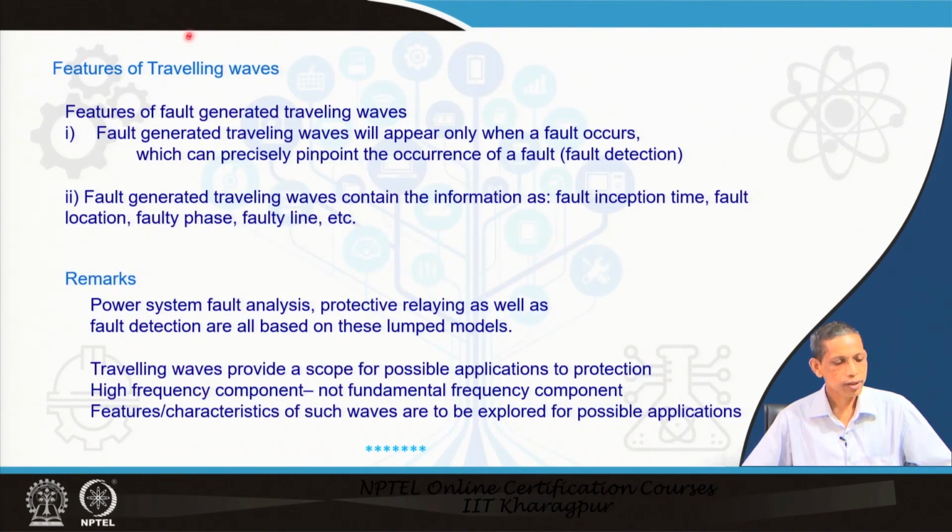Now the features of travelling waves. Fault generated travelling waves will appear only when a fault occurs. We can discriminate between fault and load change, which can precisely pinpoint the occurrence of a fault, or it can be used for fault detection. Furthermore, fault generated travelling waves contain information such as fault inception time and fault location where it has originated. We said that Bewley's lattice diagram can be correlated to that. So, the travelling time of the wave is indicative of the location of the fault.